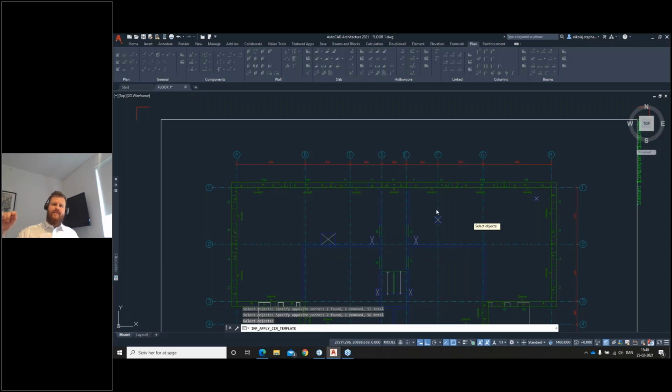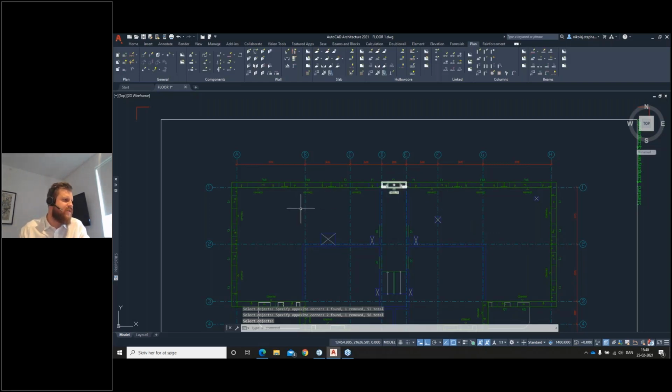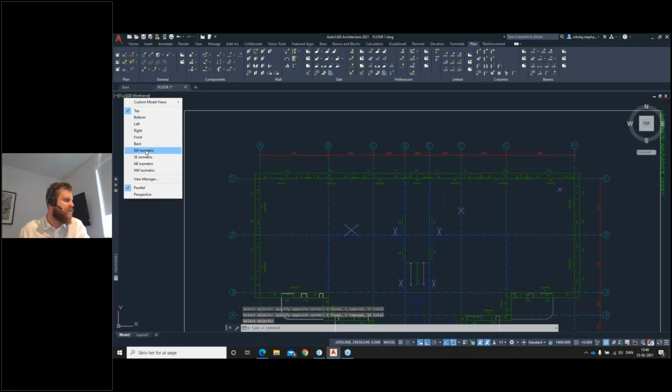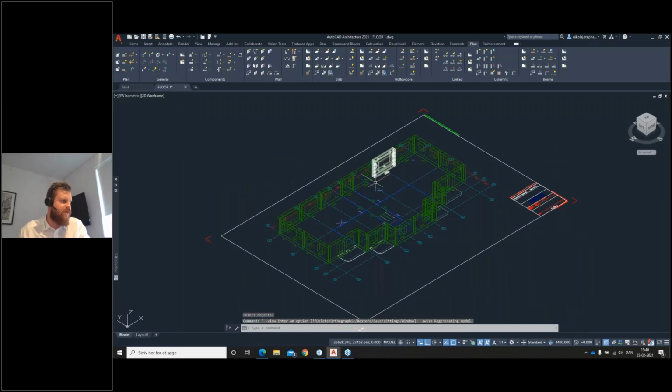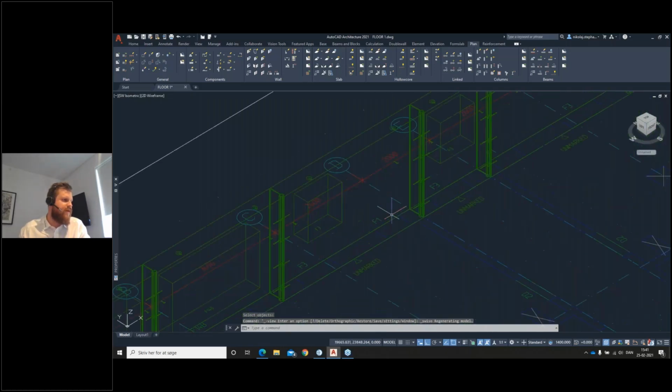And what it does now is it scans all the external perimeters of the elements, finds out how many wire loops should be put in, and it'll put them in 3D and the number that is needed to add the wire loops. And you can see it working through it here, of course. And it's already finished just while I was talking a little bit. Now you can see there are some wire loops as well.